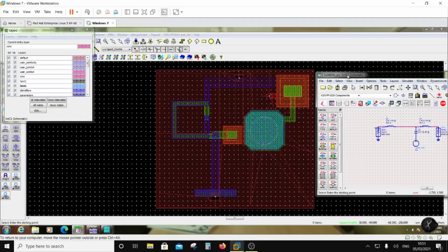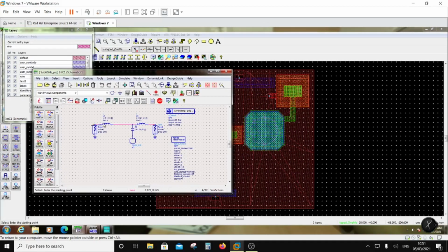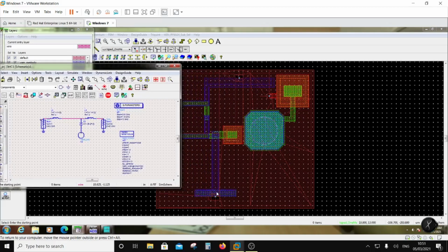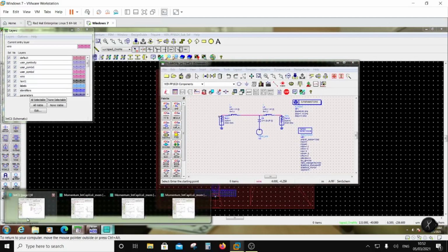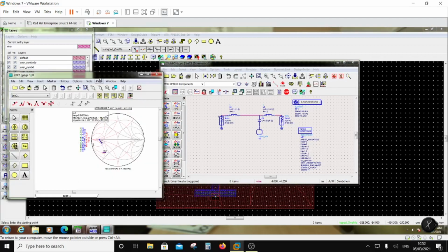Okay, so at this point, the interstage is an L, a C, and an L. Now this L is so small that this is just a piece of line from one transistor to another one. That's a piece of line, and then there is a shunt capacitor over here, and then there is a series inductor going to another transistor over here, and then there is a C which is used as a bypass on the gate of the common gate, right? So this results in a simulation. EM simulation results, they look like this.